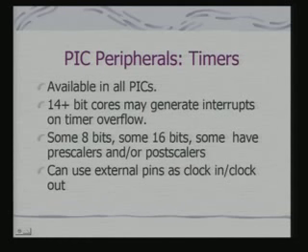Some timers are 8 bits, some are 16 bits, and they have prescalers as well as postscalers. In fact, not all of them have both, some of them have one of them, and some can have both. And they can use external pins as clock in as well as clock out. So, it is not that all these timers are being operated by the internal phase clock, the processor clock.